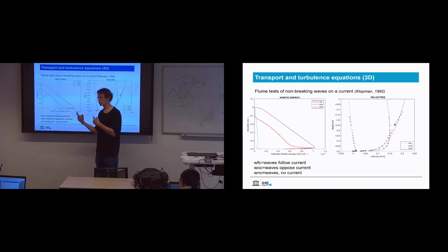So your turbulence based on the velocities of your old time level gives you a new turbulence that goes to a new vertical diffusivity or viscosity, which gives you a new updated vertical profile of the velocity, which gives you a new shear of the velocity, which is again a new production term for the turbulence. So you have a constant loop and exchange of information over time. Yeah? And then you get this sort of result. Is it clear now?